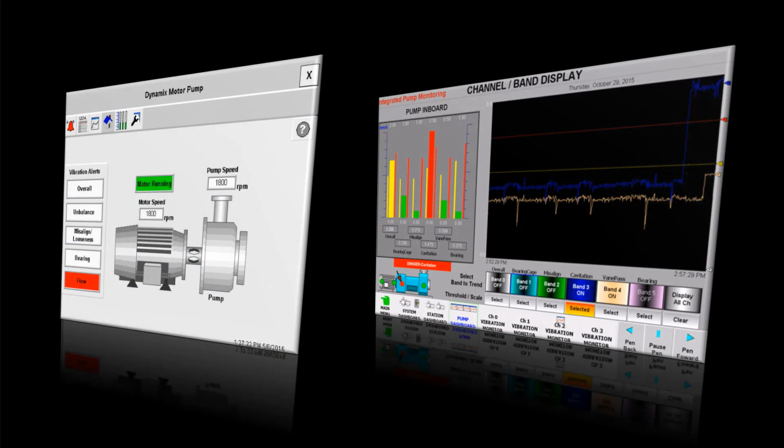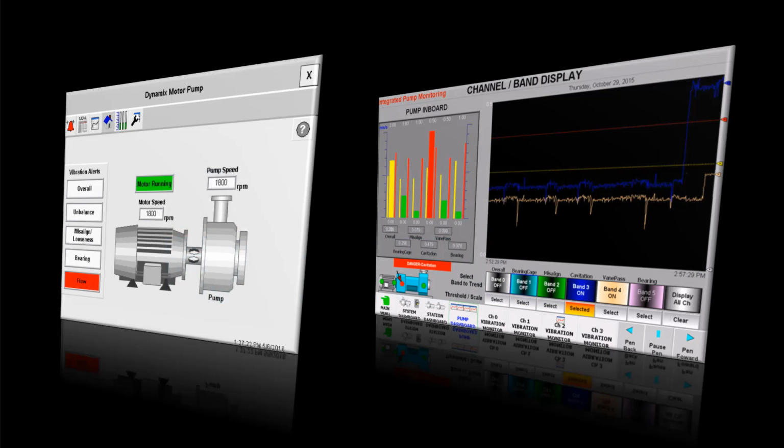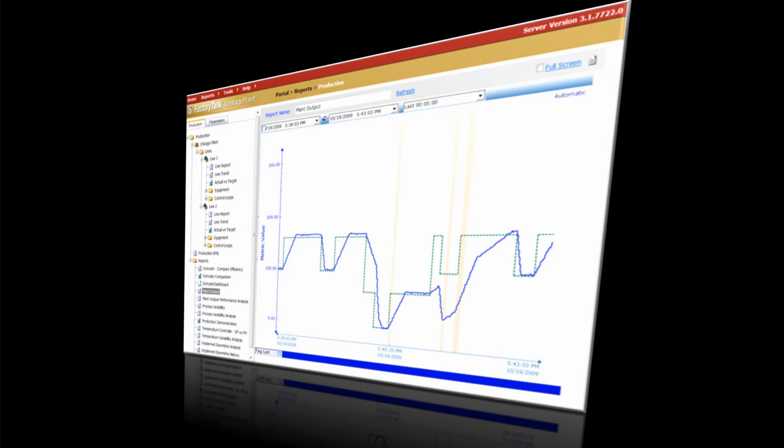So once we have tags and logic, it's very easy to implement solutions. It's no different than implementing solutions using any other I/O. Of course, there are faceplates and toolkits available to help implement a solution. Almost always customized for what you want to do, of course. Sometimes, though, the solution may be to add the tags to VantagePoint or a historian so that the data can be correlated to other processes. It doesn't matter what you do with the data, how you present it, where you present it, it's simply tags.